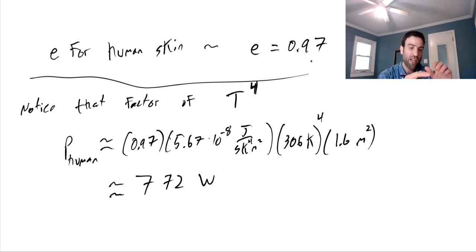So on the one hand, say you've just wrapped a piece of hot food in aluminum foil. Aluminum is a really good conductor. And so the food starts to lose a lot of heat by being conducted through the foil and then to the air next to the foil. On the other hand, that shiny aluminum foil will reflect all of the thermal radiation that the food is trying to give off, right back at the food, keeping the food warmer for really quite a lot longer.